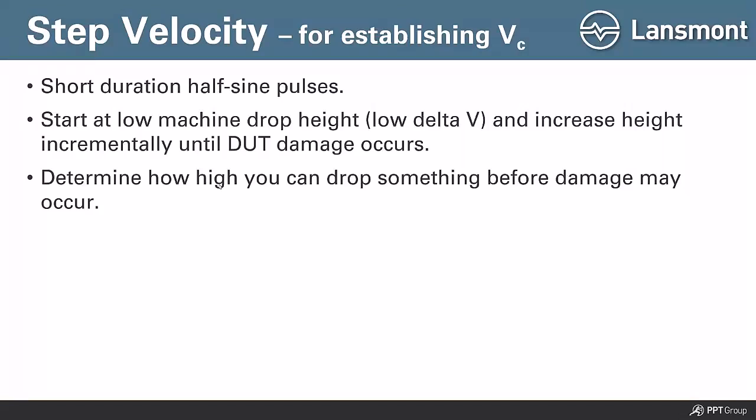Again, it's telling you how high. It's not how many Gs it can take from that height. It's basically saying, how high can I drop this thing all on its own before I would expect that damage to occur. And this goes back to that chart I had at the very beginning: product plus package has to be equal to or greater than the environment.